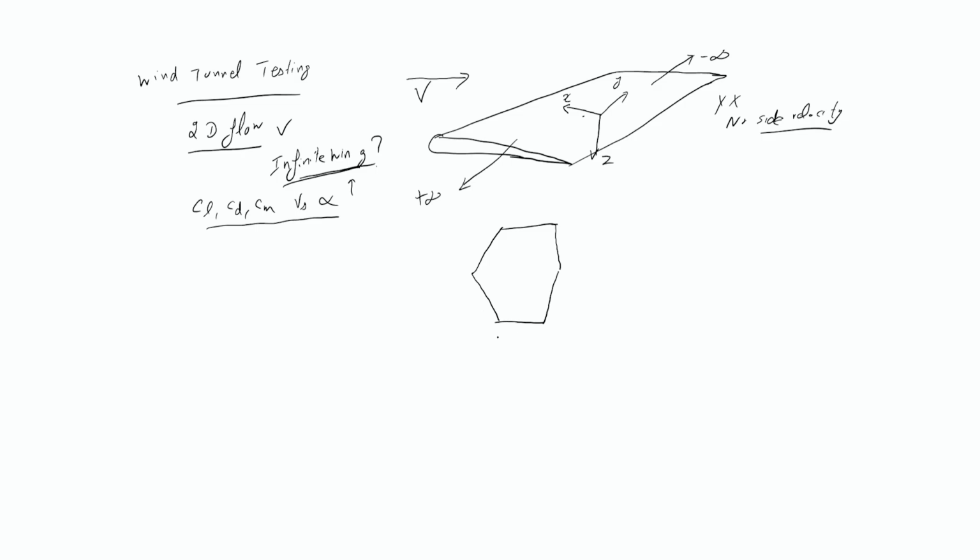Now consider this as a left wing tip and this as a right wing tip. This is the free stream velocity. From the complete left hand side, starboard, to the port side, this is nothing but the wingspan. And we denote it by a small letter b. So as soon as we know this wingspan b and we know the wing area S, we can actually calculate the aspect ratio of the wing.